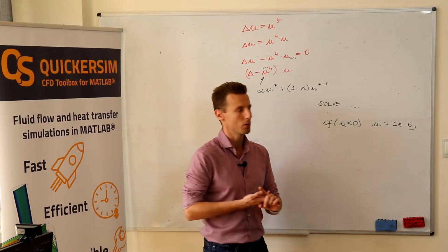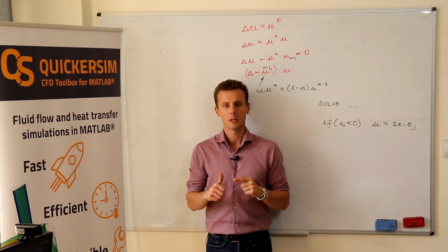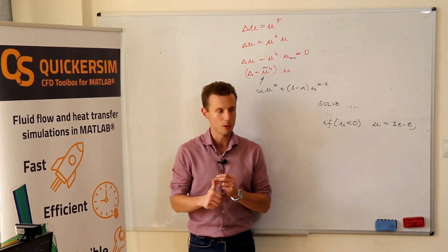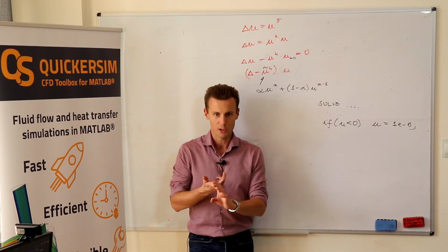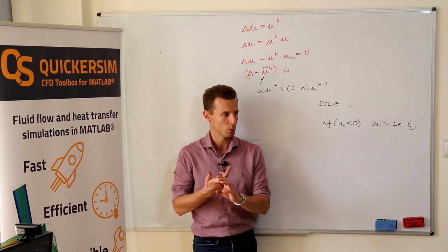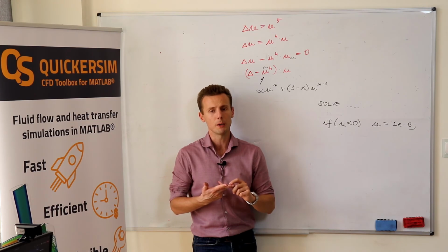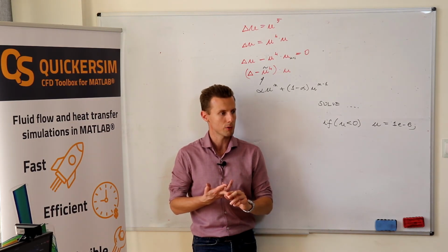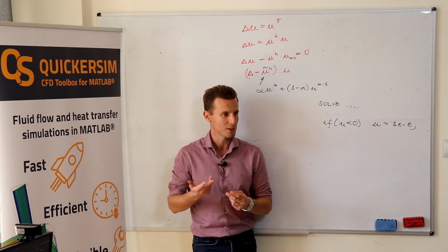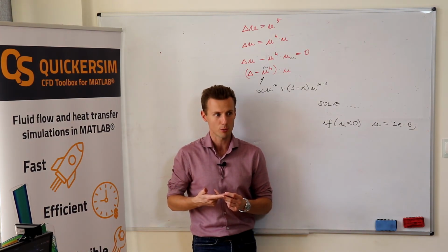And that's where you certainly need to keep in mind all the techniques for proper time stepping with higher order time derivatives if possible. Certainly linearization is something that you will be doing all the time when dealing with CFD problems or even custom applications. You will probably need linearization or a Newton-Raphson method when you deal with radiative heat transfer, like the source term in radiation is temperature to the power of 4. It's already strong enough.